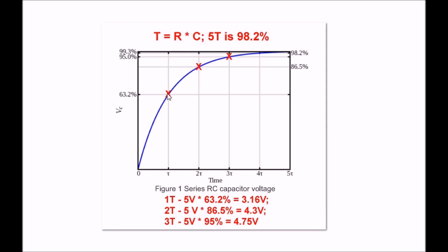But a lot of MOSFETs take a little higher voltage to turn completely on. You could still have the danger of cutting on 2 or 3, and maybe number 4 cuts on out here. See the problems? You've got noise, they're not firing together.